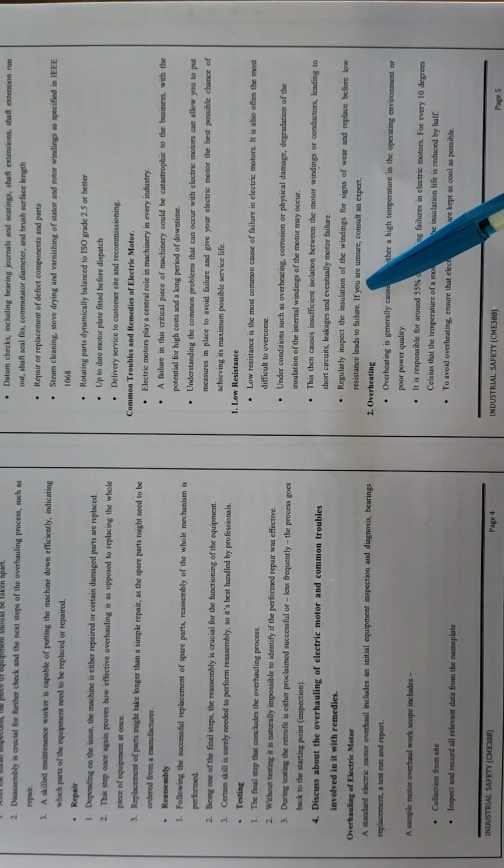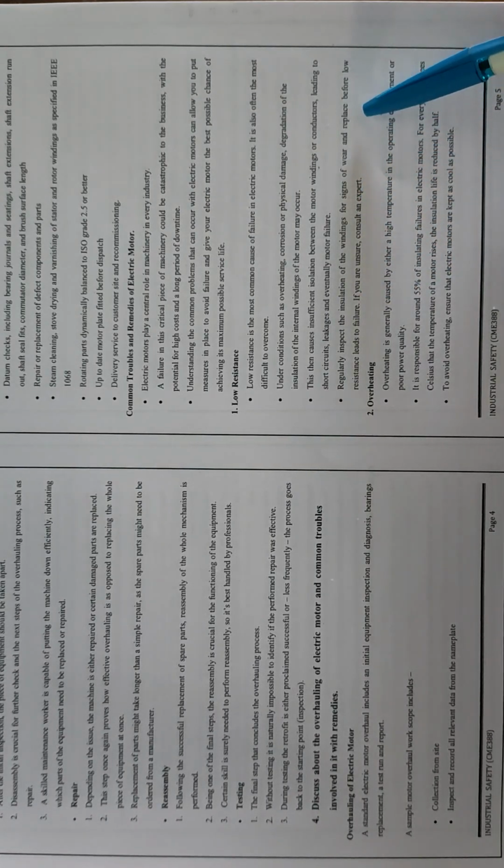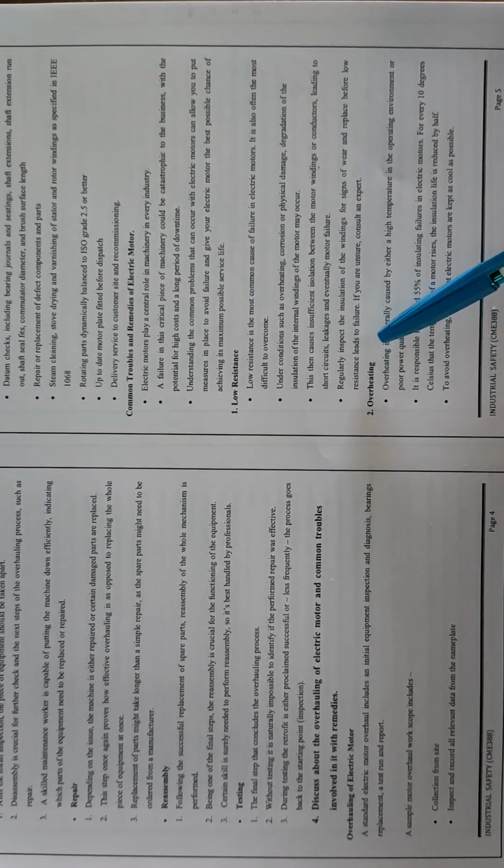Regularly inspect the insulation of the windings for signs of wear and replace before low resistance leads to failure. If you are unsure, consult an expert.